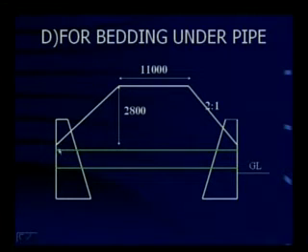A part is embedded here, a part of it is embedded here. So you have to make an excavation only in this area, only the area which is between the walls. No excavation is required for this length because this part is embedded inside the wall. So when we make the length calculation, take the total length and subtract the length of pipe which is embedded inside the head wall. This is how it goes.